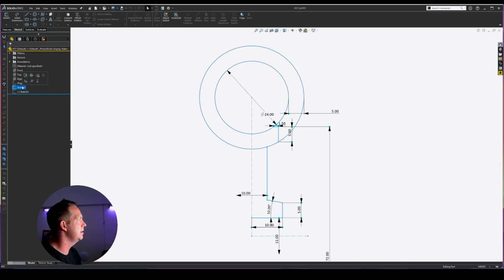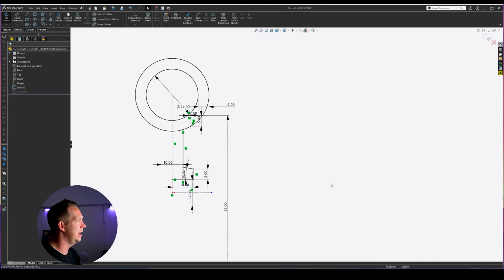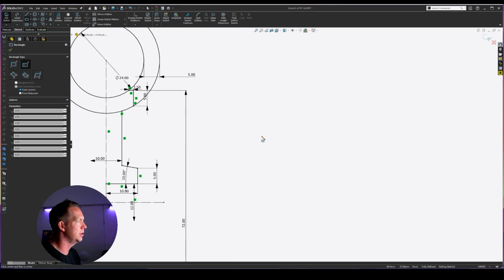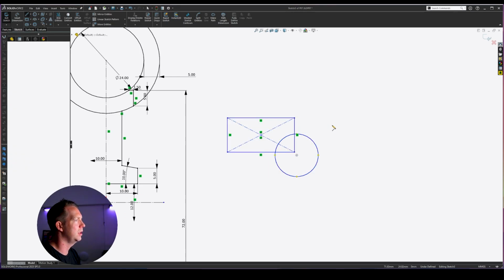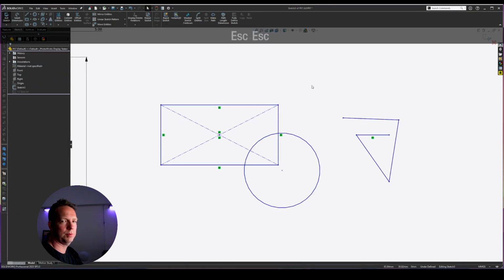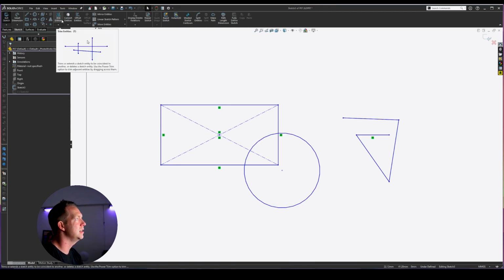We want to edit the sketch, and first I'm going to explain the trim tool for you. We will edit this sketch shortly, but I just want you now to draw a couple of other shapes, a couple of lines, just like that. Just play around. Create a few things on the screen, and then I want you to hit trim entities. Now, trim entities here has a hotkey. I've set it with a hotkey of the letter T.